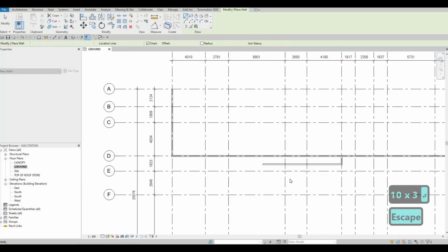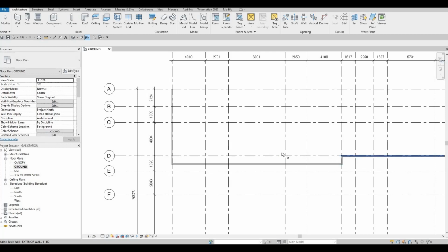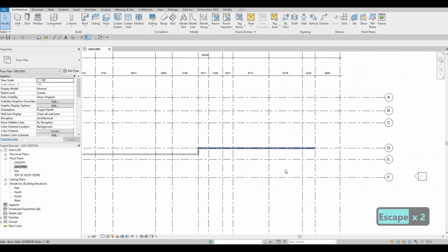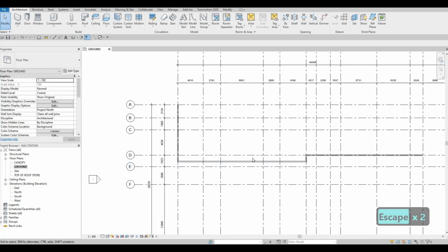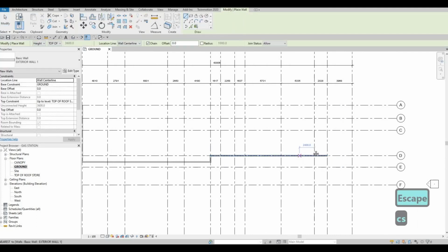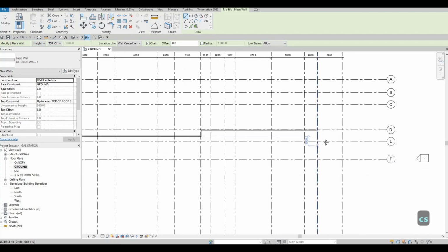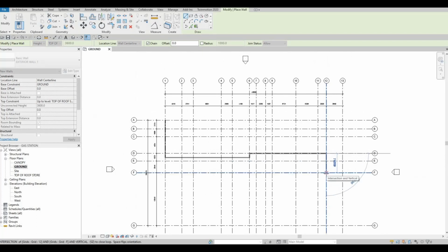And then we could just select it right there. Now, what we're going to do is TR, trim and extend, right there. And then here, we're going to put trim and extend. So that's just a quick way of having that indentation right there, just 1000 millimeters. And then we could start this one again, CS. I want it to be at D12 again, going down to F12.